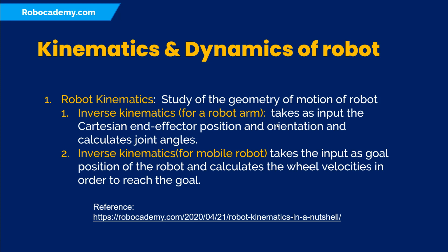Okay, if we give the position of the end effector as XYZ, roll, pitch, yaw, the position is here. The final goal position for the robotic arm gripper or end effector is here, and the initial position of the robot is here. Using the inverse kinematics equation, if we give a goal position, the equations will solve the joint values to reach this position. If you have any confusion, you can ask.